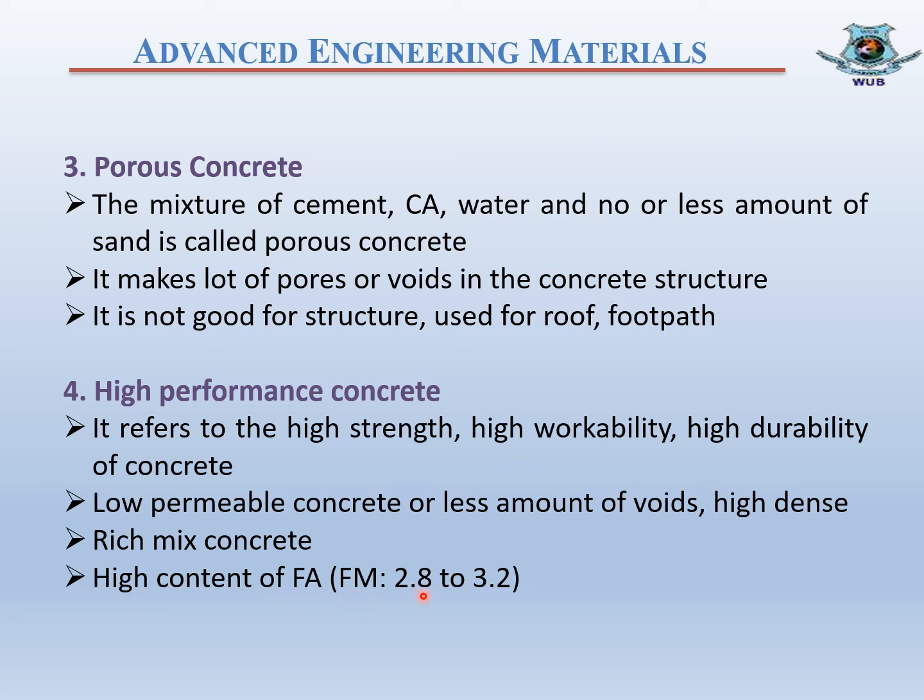and the FM of the fine aggregate is 2.8 to 3.2. At the present time, high performance concrete in developed countries usually refers to a concrete with 28-day compressive strength beyond 70 to 80 megapascal.